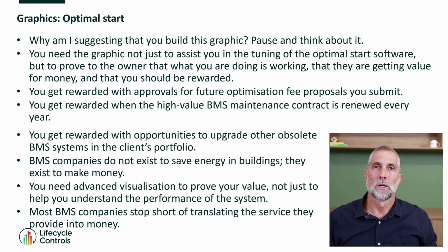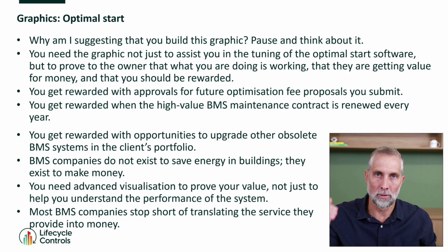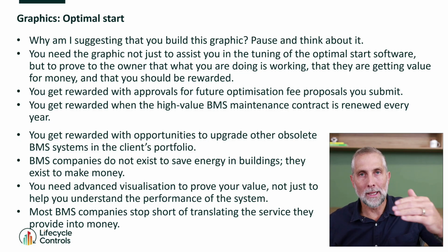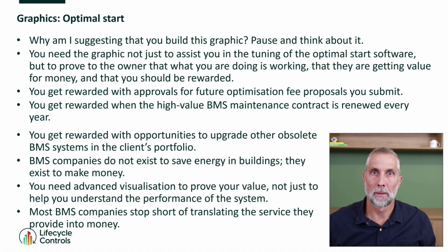So there is a kind of indirect relationship between the air handling unit supply temperature set point reset and the air handling unit supply pressure set point. There's an indirect connection between the two of them. Colder air slows the fans down, which saves energy.